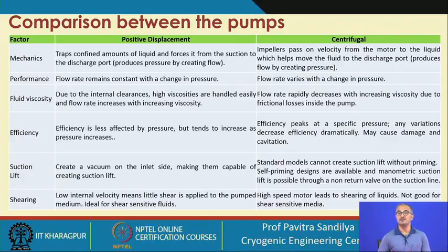First we need to drive out the air, and for that we often pour the particular liquid which needs to be pumped. The liquid is poured from the delivery side, so that all the trapped air is taken out from the pump, and once it is taken out, only then will the pump be able to suck again.